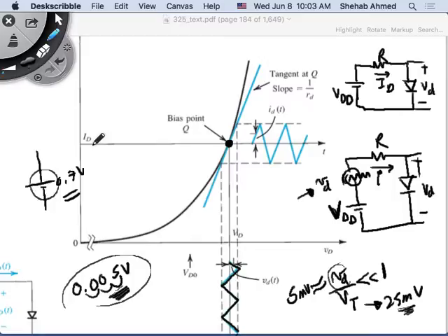So, how would you find those? Only consider VDD and the resistor and the diode, forward drop of 0.7 volts. Forget about this small v for a while. If you do that, you can find this, right? After you have found this, you know that your signal is small, 0.005 volts, much smaller than your 60 millivolt range, or much smaller than 25 millivolts, right?